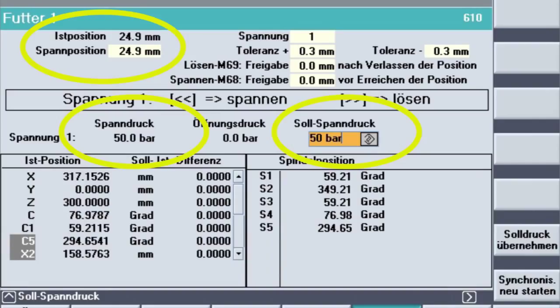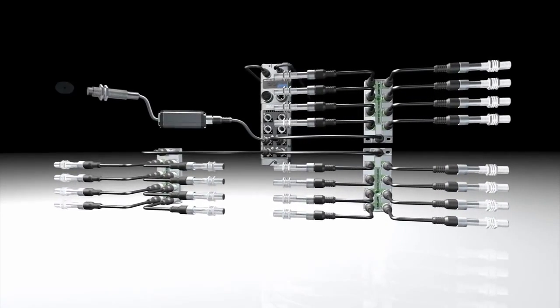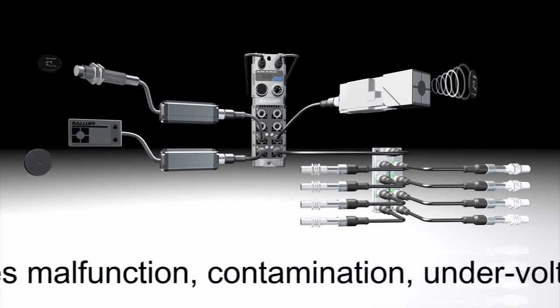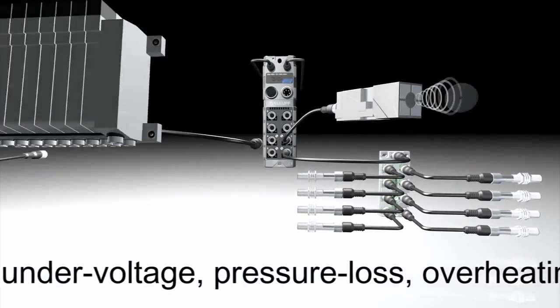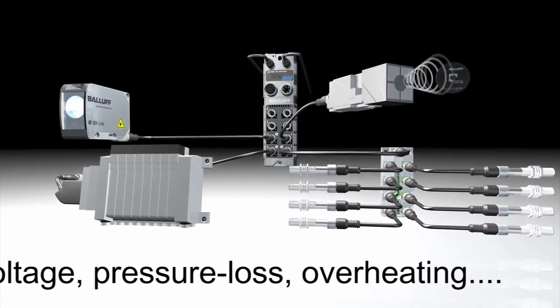Instead of frequent preventive maintenance, service can be need-based and helps reduce machine downtime. With IO-Link, faults can be diagnosed at an early stage, so that precautionary measures can be conducted ahead of time and thus help increase equipment reliability and operational availability. IO-Link devices can provide information about the device status. Examples for diagnostic messages include malfunction of the device, contamination, undervoltage, pressure loss, overheating, time exceeded, etc. Cable break, loss of communication.